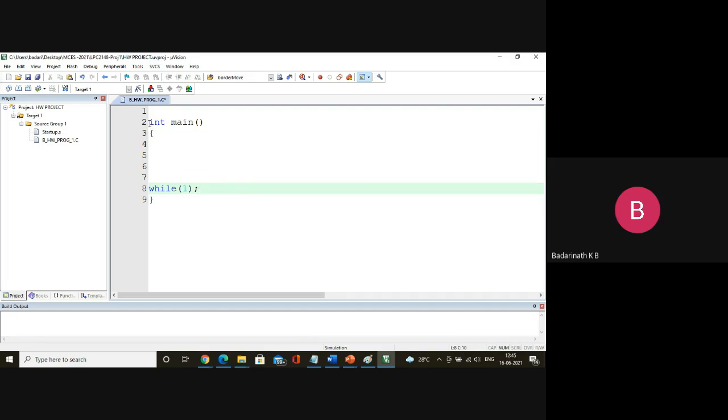Whenever we write an embedded C program, as we know there are a lot of hardware details of the microcontroller, I'll be using them to start implementing my logic. For example, I said in the beginning of the project you should define the function of each pin, for what purpose you're using the pin. Am I using it as a GPIO? Am I using it for a timer? Am I using it for an ADC? For that, I said you have to use the pin selection registers.